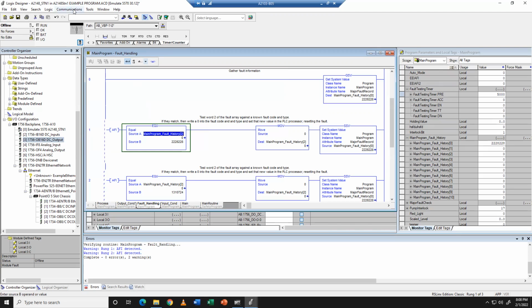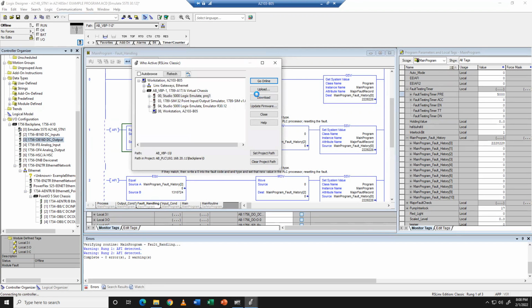If it is some sort of control or programming error, somebody entered a funky set point or preset, or you overflowed. Overflow meaning, remember when we were talking about integers and double integers, if you have an integer try to write higher than 32,767, it can't, it doesn't exist, and it'll fault the controller.